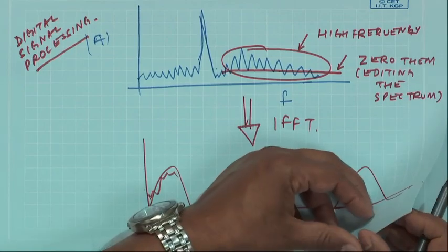The reason we are studying this filtering is because in CBM, when we have transducers, when we have signals coming out of the transducers, these effects do happen, these issues do happen. So, by proper choice of the signal conditioning equipment, by proper choice of setting the signal filters, we can eliminate some of this problem.